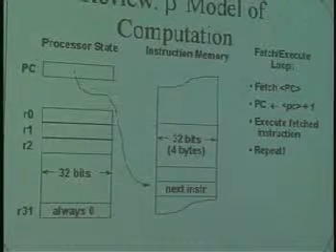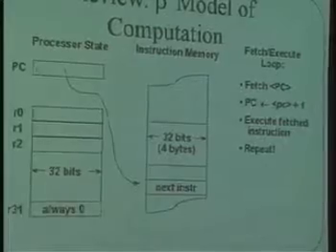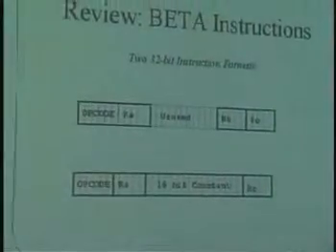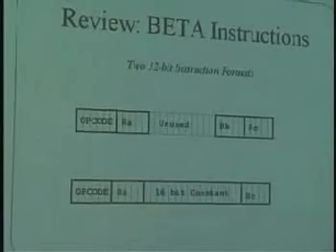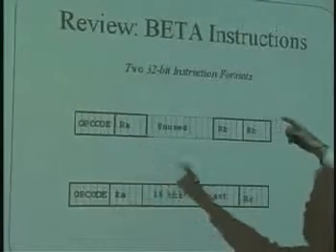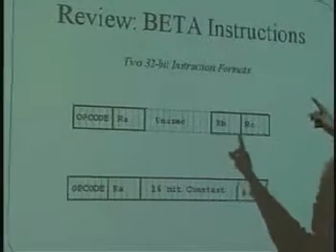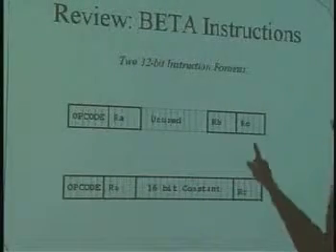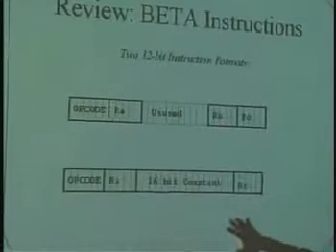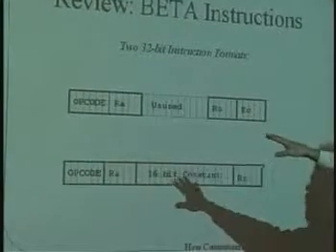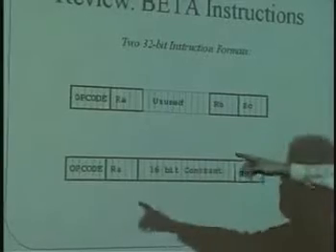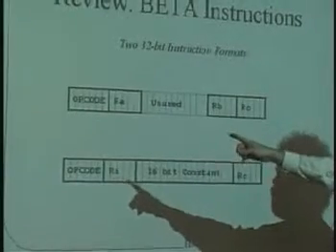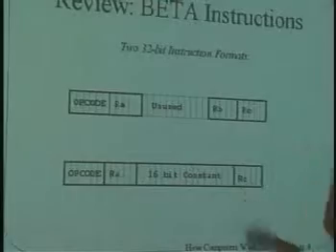And that'll be important in understanding where these plus ones come from some of the time in the system. Again, here's the format of the instruction. We had 6 bits over on the left-hand side that told us the opcode, and then we had 3 operands. If they were all registers, there was RA over here, 5 bits. This stuff wasn't used. RB over here, 5 bits, and RC, that being the destination. And in the case where we wanted to substitute a 16-bit constant instead of the contents of RB, we had just this register RA followed by the 16-bit constant followed by RC.